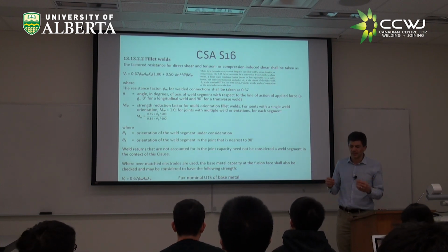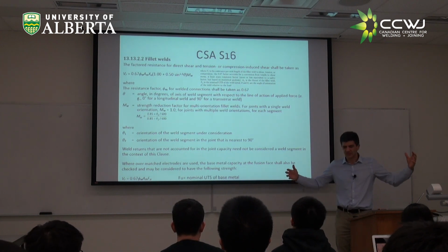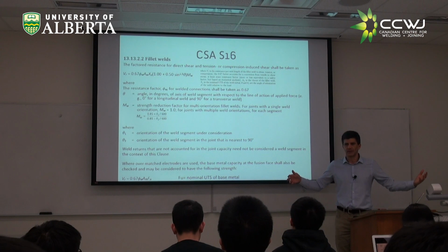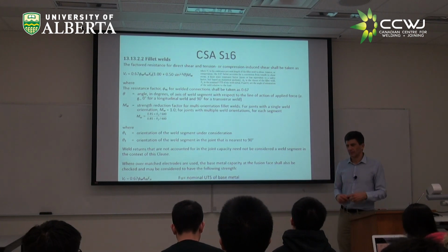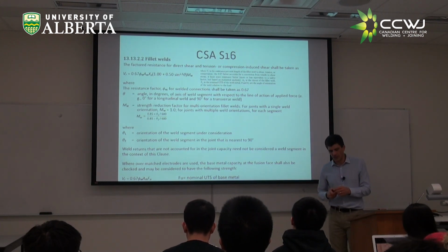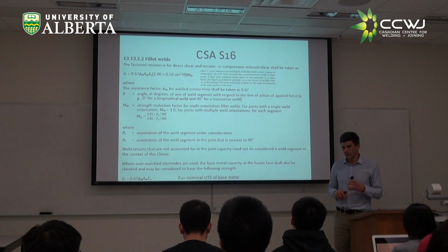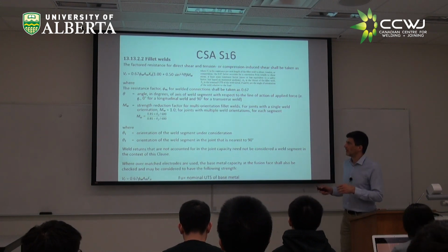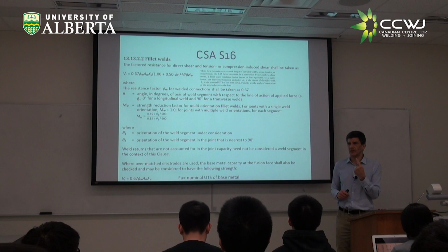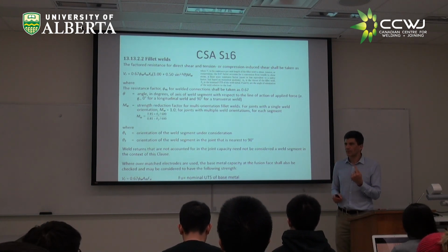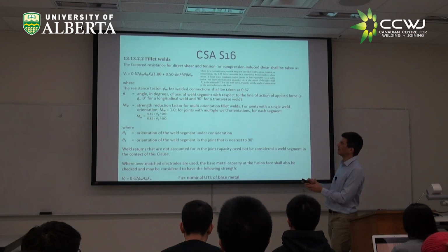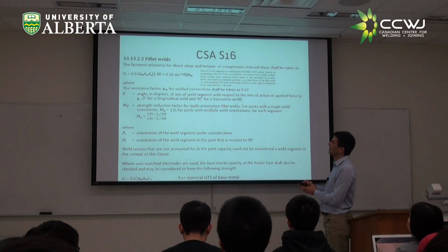But overall, the size of a weld, the width of a weld, is very small compared with the size of the component. So, I don't know who, maybe Dr. Omer Blodgett at Lincoln, I'm sure many of them also came up with this at the same time. They said, the weld is so narrow, we're going to consider it as a line. And this line has one property that matters, which is how much force it can take per unit length. That's the one property of the line, and that's all we care about. And here's the force it can take per unit length.